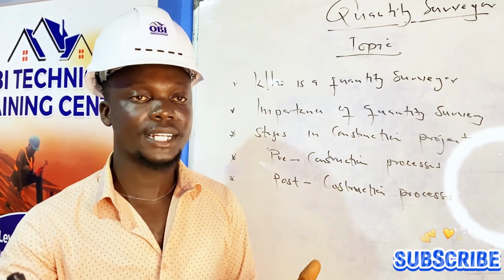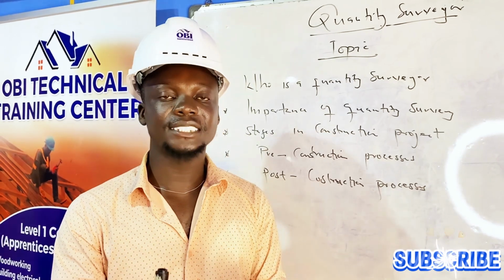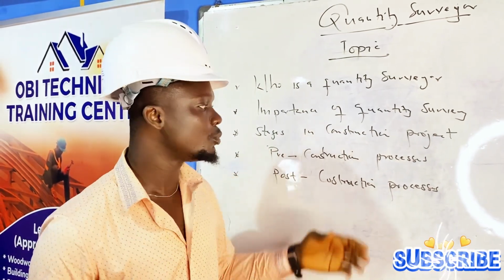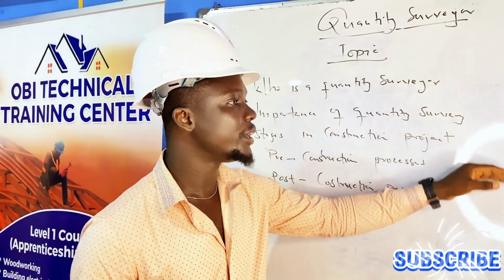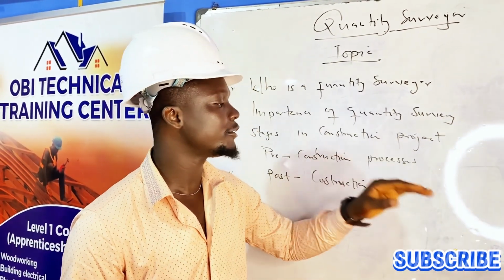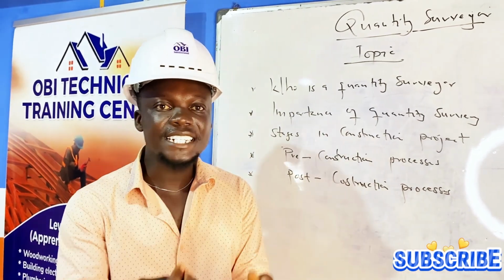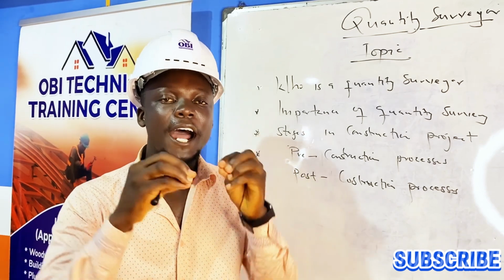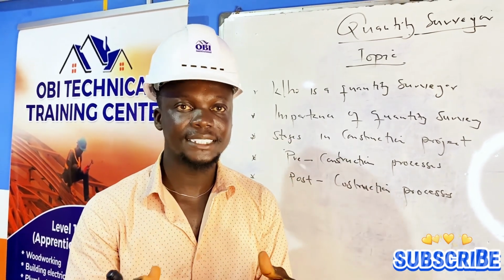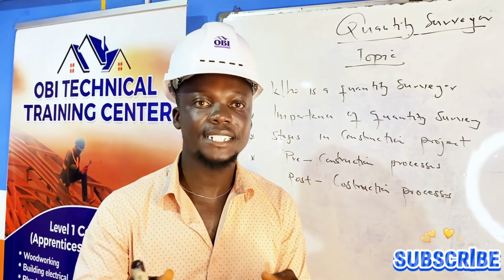That is under the post-contract stage. That is where a contractor employs a quantity surveyor to manage the resources on site. Yes, so we have what we call a breakdown, that is preparing of the material schedule, preparing of the labor schedule, and preparing of plant and equipment. That's what we call the operational bill. The operational bill is in there to guide the contractor on how much he or she will spend in order to complete the project, and the profit margin the contractor is also getting at the end of it.